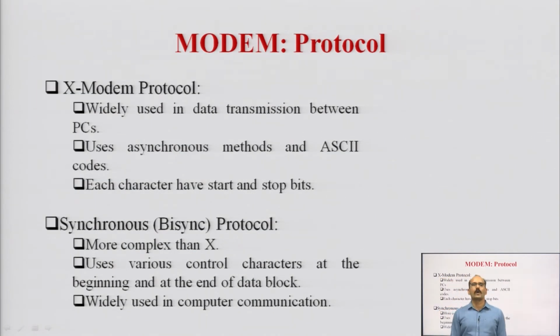Now, we are going towards the protocol. Basically, when we are talking about the modem system, it is going to transfer the data in the digital format. When the data is transferred in digital form, some protocol has to be followed. That protocol is going to give us the frame structure, or the structure of the individual packet that is going to be transferred digitally. That is why in modem basically they are using X-MODEM protocol and Synchronous Bisync protocol.